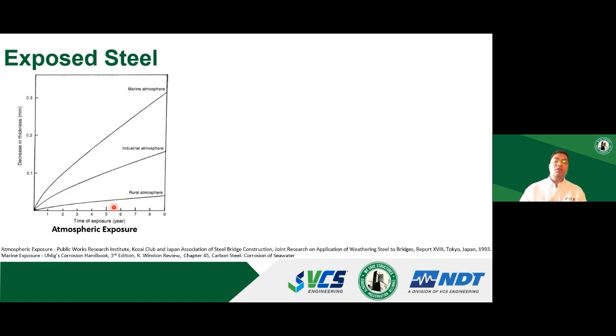So we need to be mindful of what kind of steel it is, if it's coated or uncoated, and what kind of environment it is, because that will help us design the structures better. Maybe we can have more sacrificial thickness, or maybe we can have more effective coating for those steels.